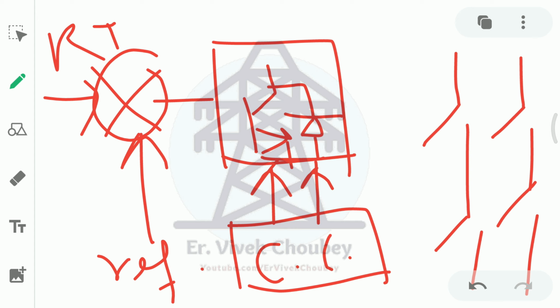These switches need to be turned on and turned off at different instants of time. So this control circuit takes the current from the comparator that is coming as an error signal. We call it an error signal instead of current. This error signal is processed by the control circuit, and based on that error, it drives the gate terminal of the IGBT. This control circuit is also known as the gate driving circuit. It sees what the input coming from the comparator is, and based on that it drives the IGBT. Now if the error is high, that means the temperature difference is high.